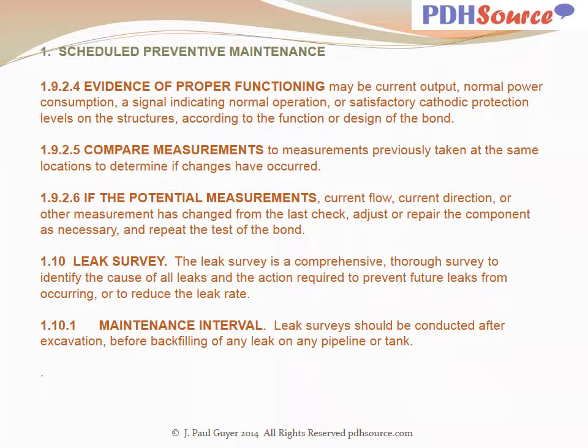The leak survey is a comprehensive, thorough survey to identify the cause of all leaks and the action required to prevent future leaks from occurring or to reduce the leak rate. The maintenance interval for leak surveys: they should be conducted after excavation, before backfilling of any leak on any pipeline or tank.